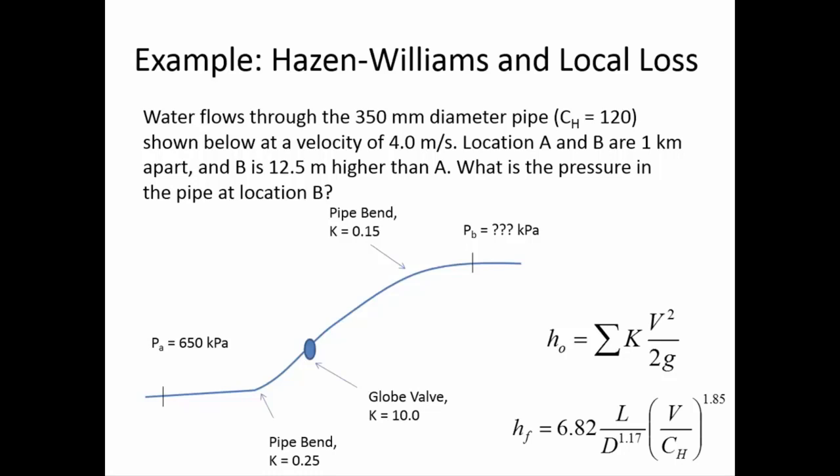If you use the average velocity in the velocity head term under laminar conditions, that would undercount how much energy is in the velocity head. So when you have laminar conditions, you're supposed to use an alpha of 2.0, but when you have turbulent conditions, alpha is 1.05, because average velocity is a better estimate of the velocity at most locations in the pipe when conditions are turbulent.